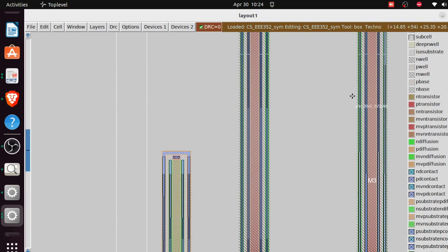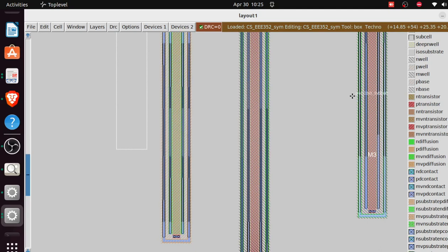I think we can also do that for the NMOS. It appears to be 22 micrometer, also too wide. When we split each device into smaller parallel devices, the maximum width should be less than 20, because we can see 22 is still long.